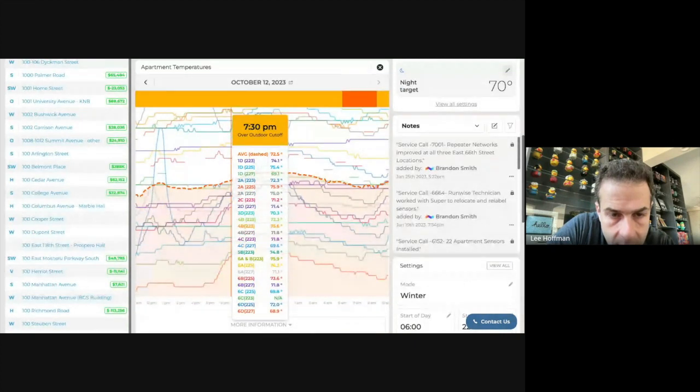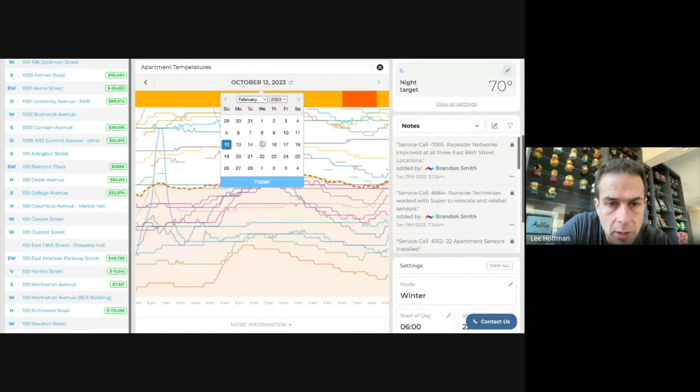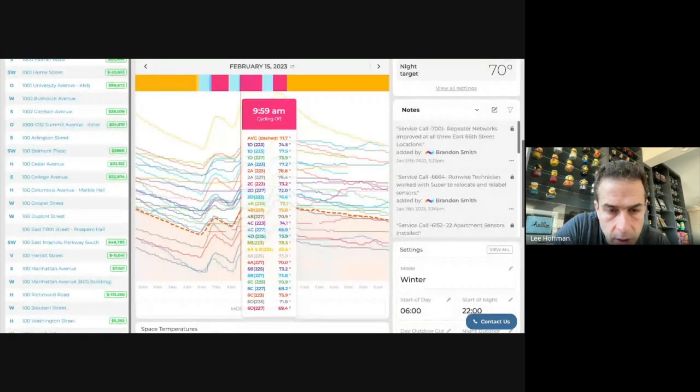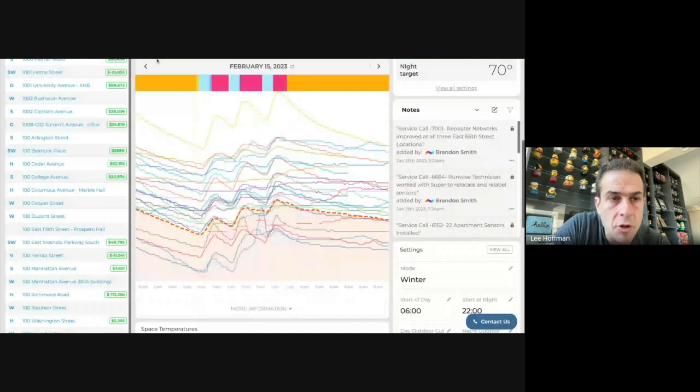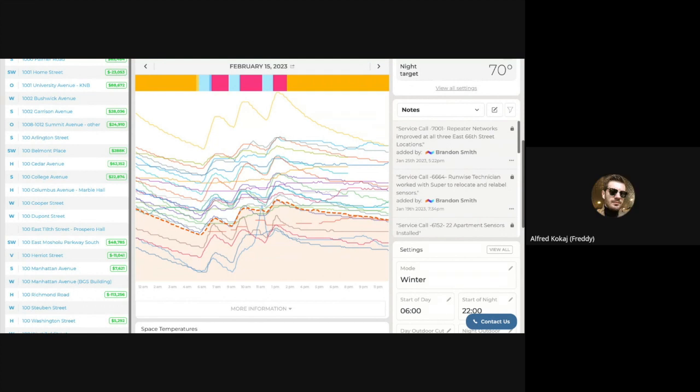6D. It's the blue one. Well, it's hard to see here. I go back to February when it was actually colder. I mean, I see it on the lower end for sure. Yeah. And when you go to that unit, have you ever used a temperature gun to take the temperature of the radiator? No, it's barely on. It's just warm. It doesn't reach full heat. And I know that the unit is maintained because there's staff who lives there.